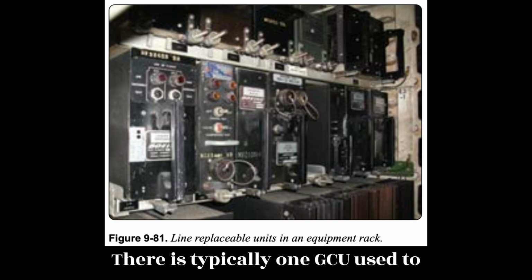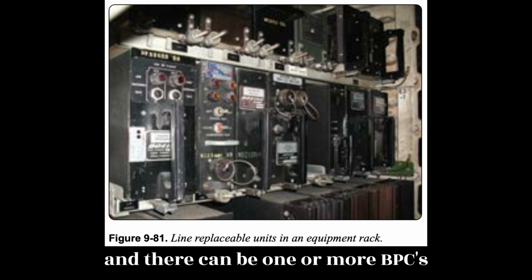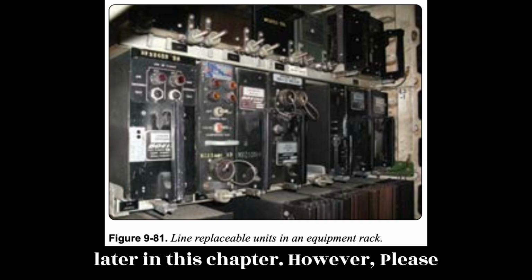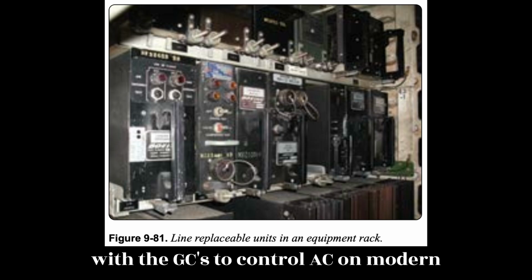aircraft. There is typically one GCU used to monitor and control each AC alternator, and there can be one or more BPCUs on the aircraft. BPCUs are described later in this chapter, however, please note that the BPCU works in conjunction with the GCUs to control AC on modern aircraft.